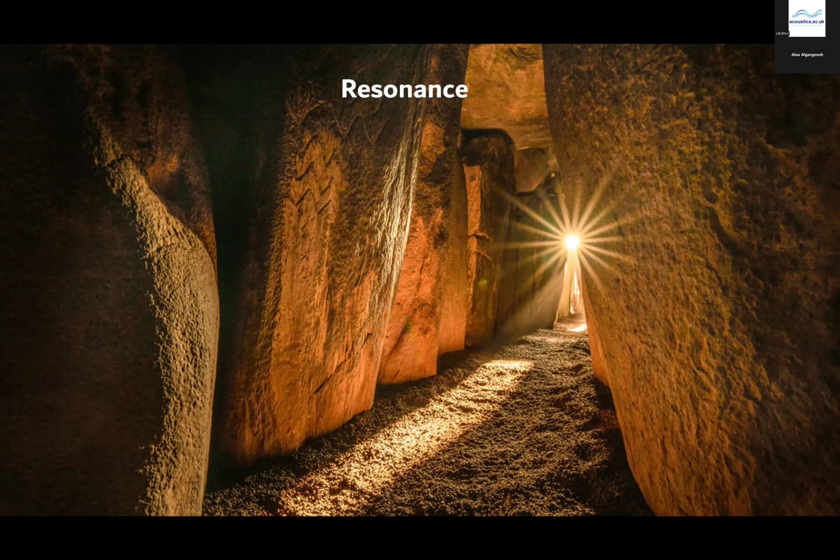But unlike recording rooms, where achieving this homogeneous acoustics is preferred, having diverse acoustic characteristics at different parts of spaces, such as worship spaces, can be favored. This acoustic variety can produce aural aesthetics, forms auditory symbols, and creates emotional experiences. Therefore, the resonance resulting from the reinforcements of specific frequency bands can provoke an emotional response that enhances the experience. And this amplification can result from the reflection from the architectural elements, such as a dome or the subspaces. And then the reflected sound can be stronger than the direct sound, especially at some frequencies.